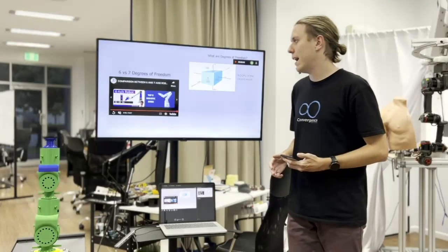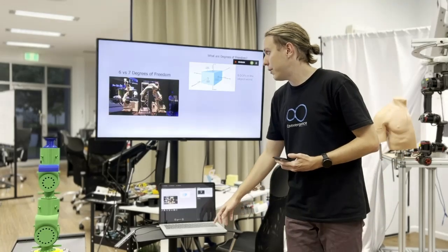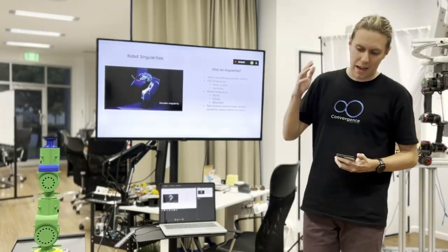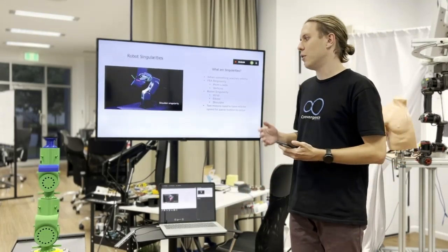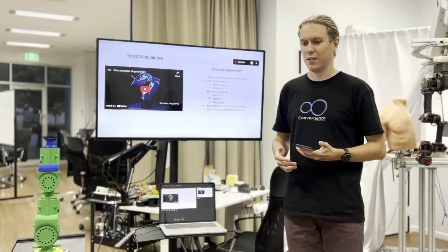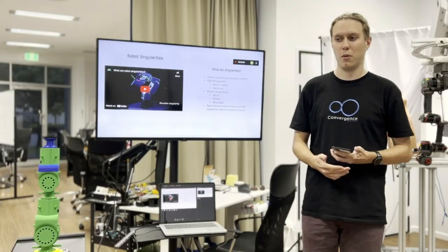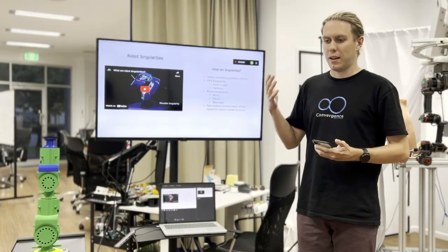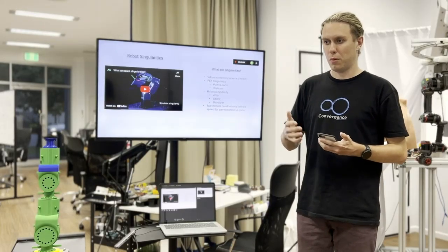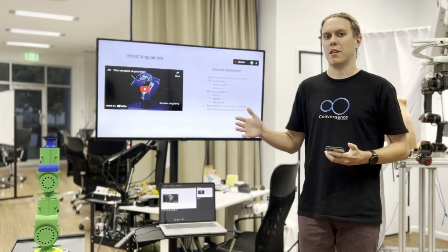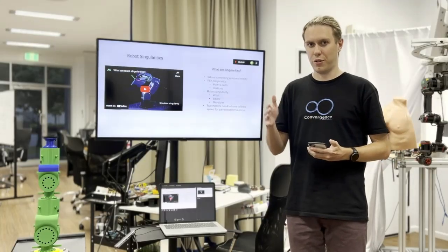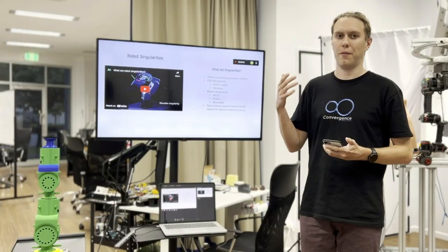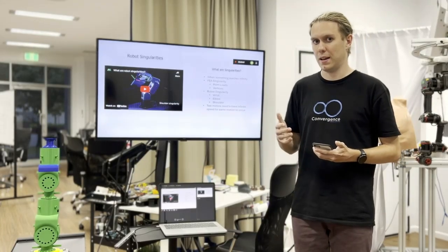The problem with that is that it adds an extra degree of freedom, adds singularities. The problem with singularities is that on a 6th degree of freedom robot and other degree of freedom robots from 5 up, it causes problems when you want to do motion in one direction. Once it gets close to that singularity, the motors will have to slow down to their maximum speed.